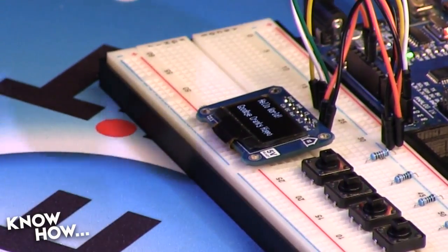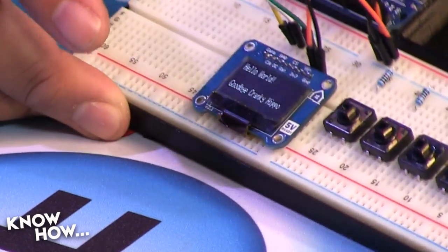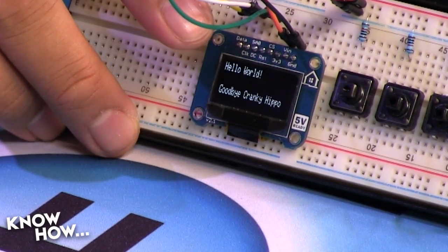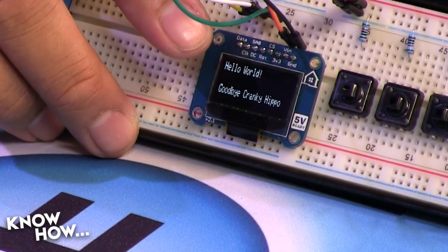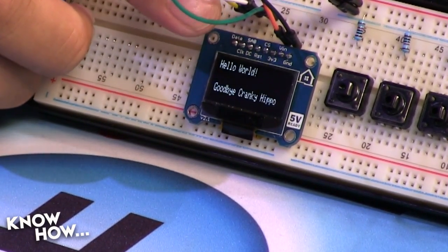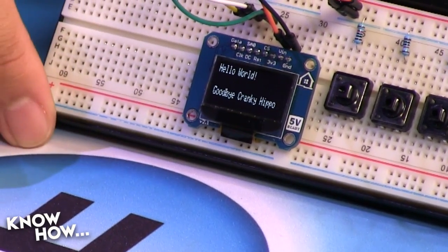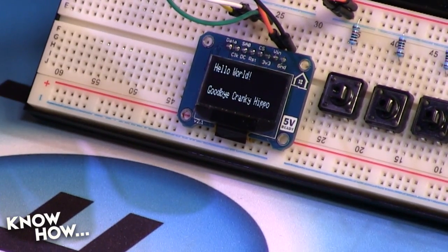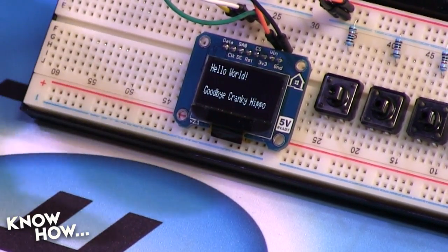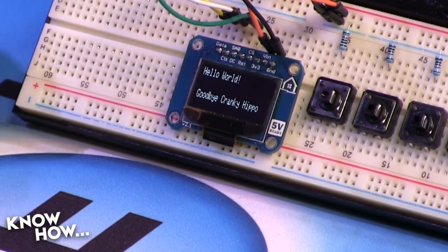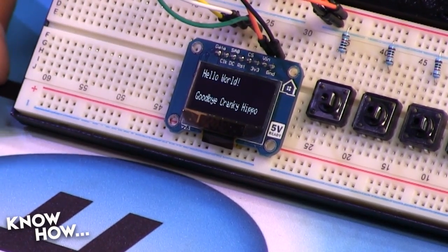There are actually two different ways to connect this OLED screen. The first is the way that we've done it with the I²C, which is super, super simple. But it's not the fastest refresh rate. There's another way where you could use all of the pins up top, but it's going to take a lot more wiring. It's much more flexible. I can do much more with the screen. But for the purpose of our project, since we just want to use it for display, not really for graphics, I²C works just fine.